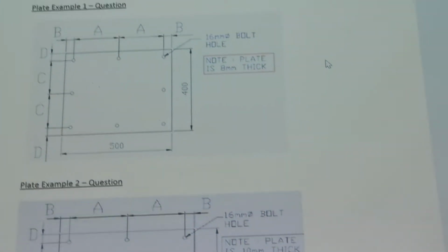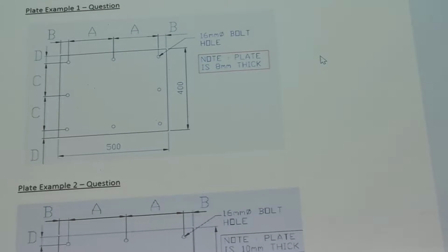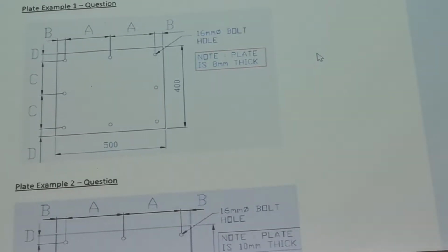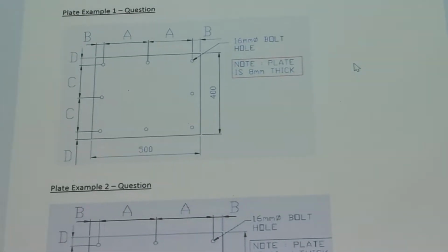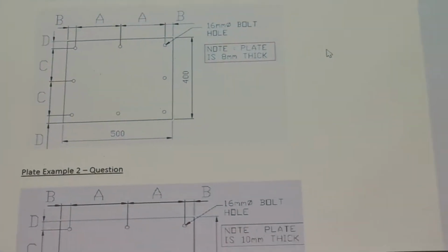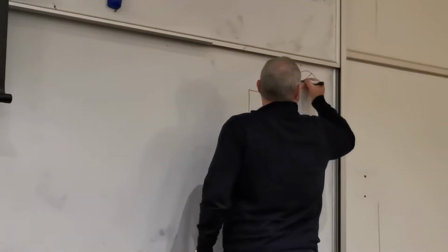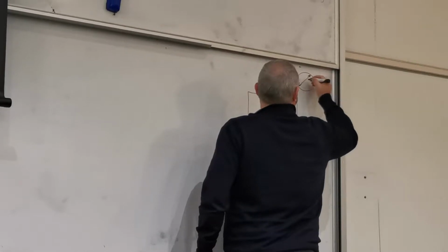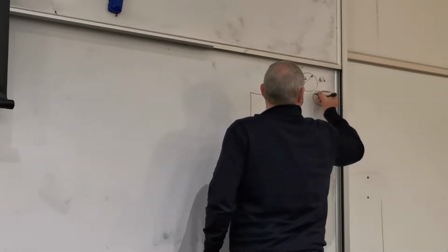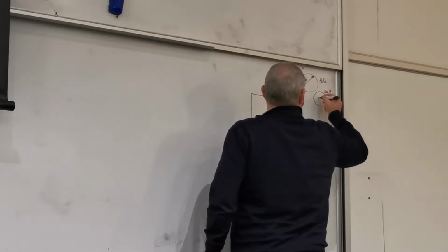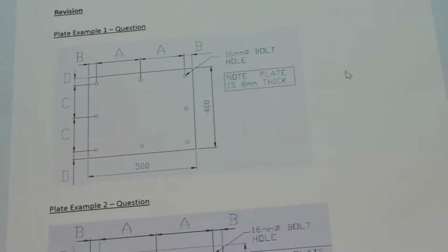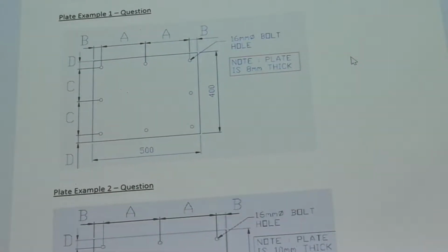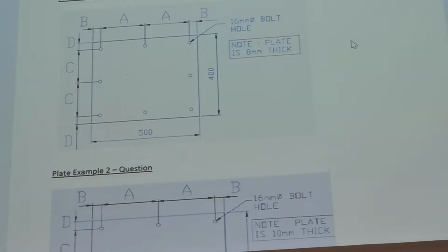Okay, well the circle is pointing at the bolt hole. That's why both of those two letters are capitalised. So that is a 16 millimeter bolt hole. It's really important that you understand that. So if the bolt hole is 16 millimeters, what is the bolt diameter on the metal? 14. So please don't do it the other way around where you go, oh, it's a 16 millimeter bolt in a hole, because you will get these calculations completely wrong. It doesn't allow for a slight mistake.